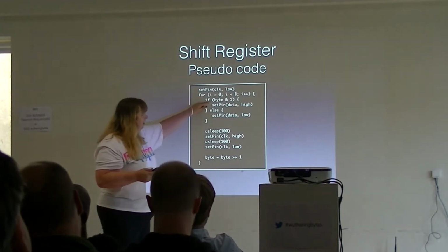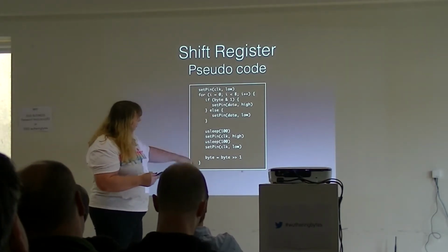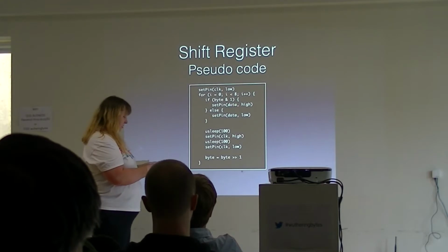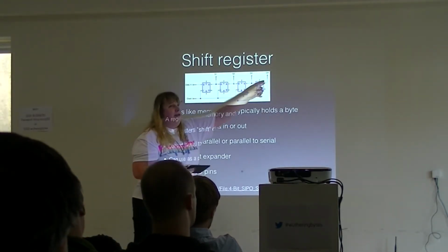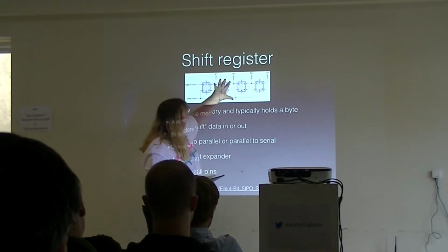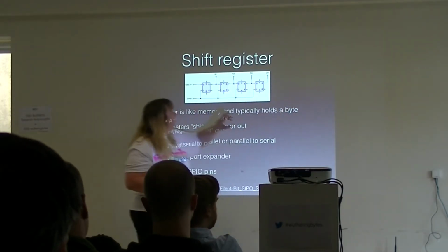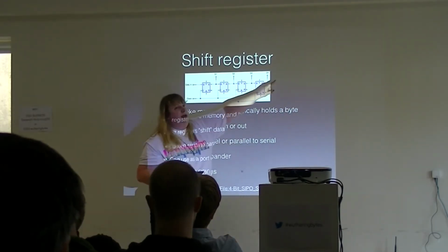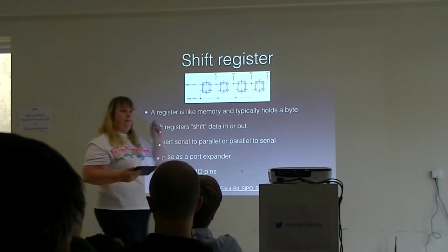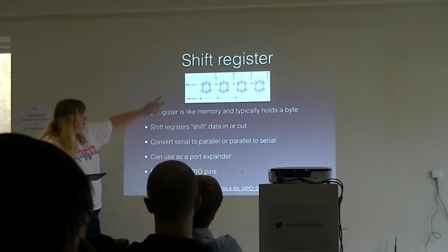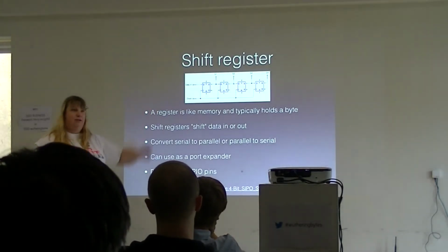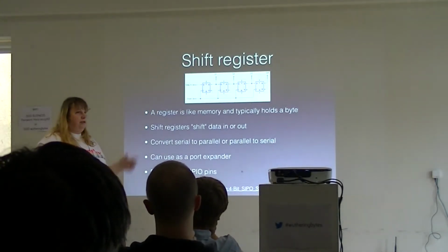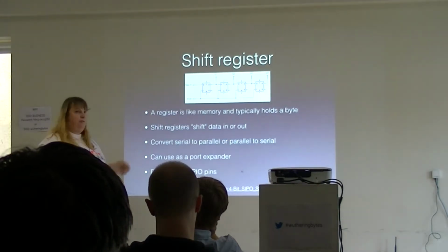And we go around again and set it, and gradually at the end of that we go around 8 times. So that's moved out 8 times, and if you imagine that's there as well, you'll have 8 output pins set to the value of the bits in your byte, just using 2 input pins. So those could be 8 LEDs, and you can set the value of 8 LEDs just from 2 pins.